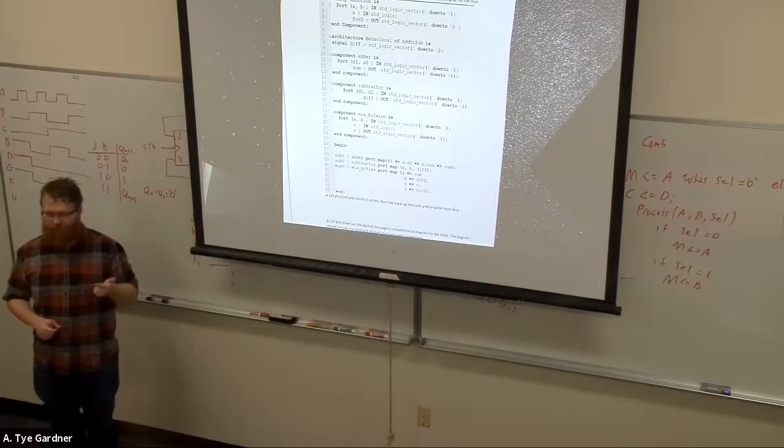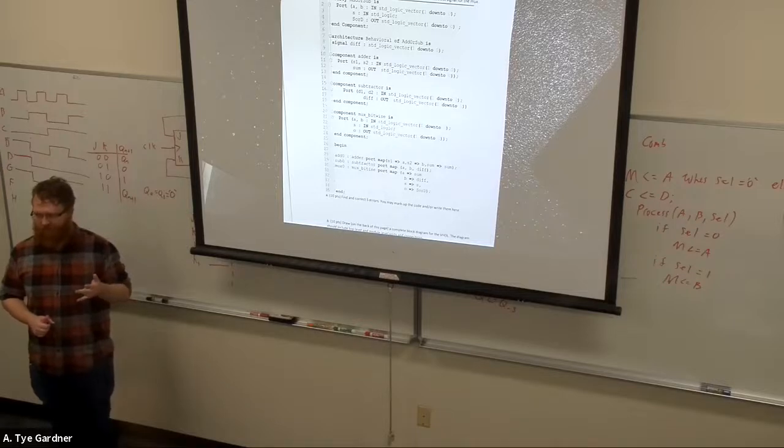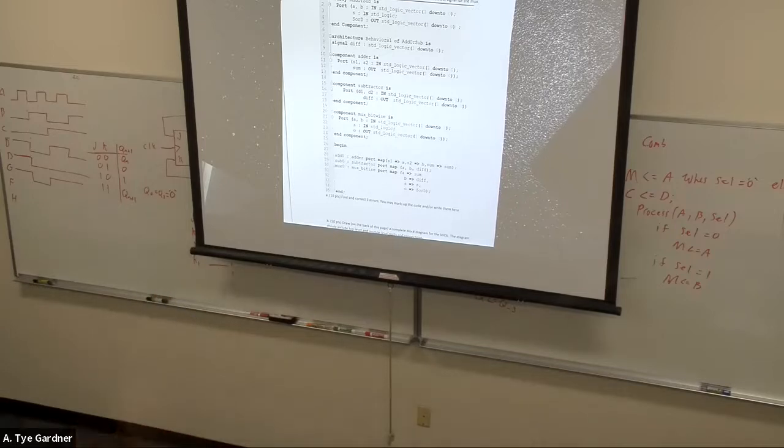On the first pass, I'm also going to check for any missing semicolons and any missing ifs, thens, or rising edge of clock. Those are the 4 big things that I'm looking for. So I'm going to go stand back here so I'm not in anyone's way, and let's start going down.